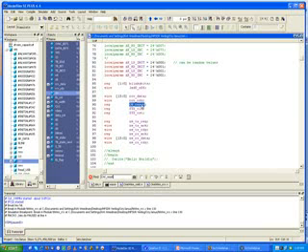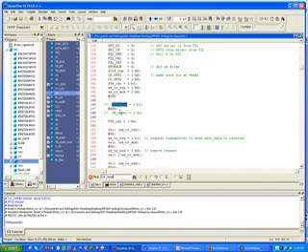Okay, there, I declared it, so I've got it. Well, I forgot to uncomment my code to do the reset here. That might help. So here in the code, in my test bench, I said OW reset equals 1 tick B1, set it high, delay this number of time units, and then set it back low. So now let's save it.